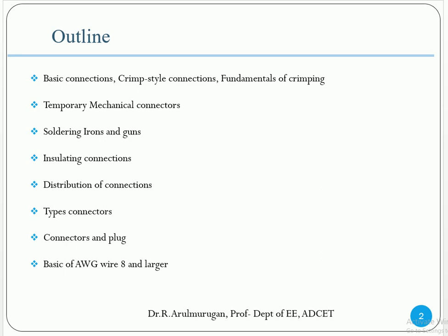So when the amps rating increases, and when the amps rating is 50 ampere, my battery is 50 Ah, voltage is 12 volt. So when ampere is increased, the diameter is more. Okay, why is the diameter more? My withstand capacity is more. So based on that factor, you will select your AWG wire.